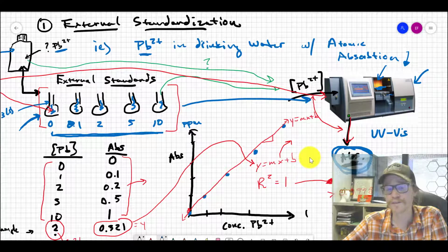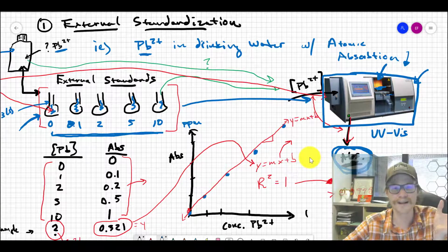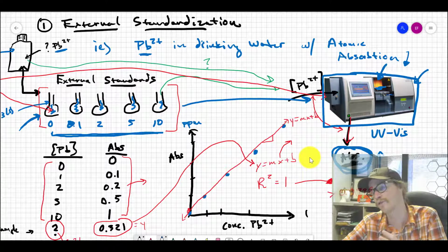That's unreasonable. You think about this, it's a physical electronic object. This has got a flame in it, right? The flame is probably going to change in its hotness between the morning and the evening. It's going to assume that the detector inside of this thing doesn't change over the day. Maybe this thing's in a room where the sun hits it, right? So in the morning the sun's not hitting it, and then at noon all of a sudden it gets direct sun. That detector starts to heat up a couple, 3 or 4 degrees more than it was before. That means the response starts to rise too, and the whole thing starts to drift over time.